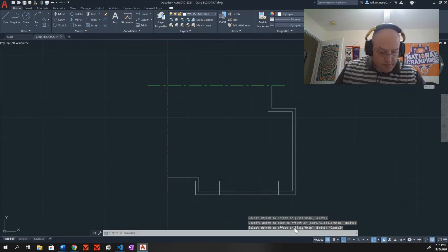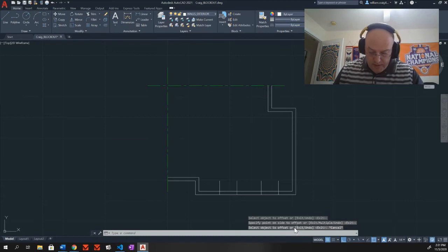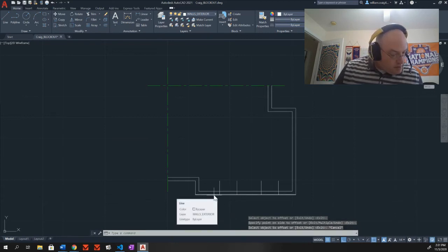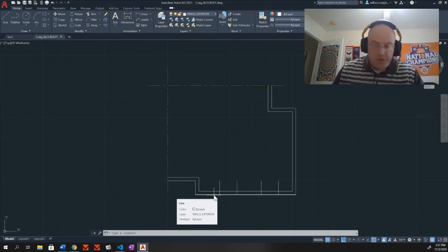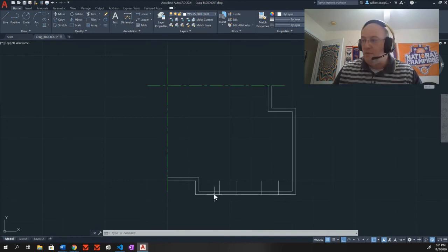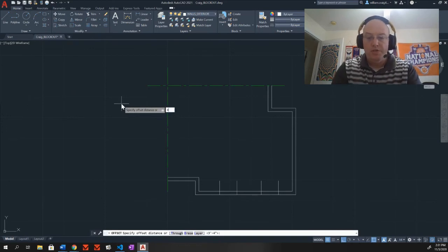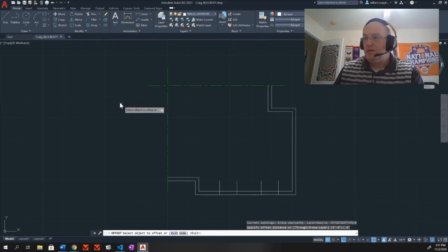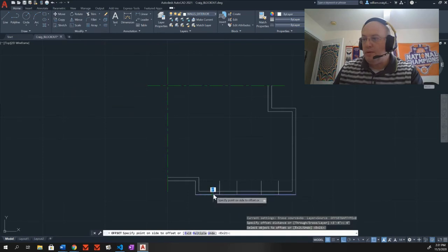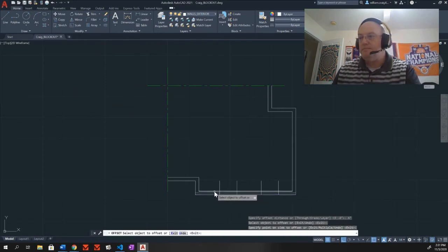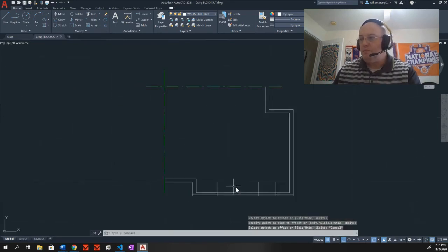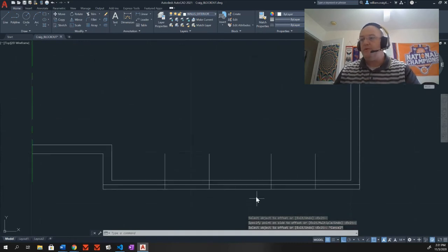And we're also supposed to offset this bottom line right here. As it says, assume that the glass is at the middle of an 8-inch thick wall, so we should be offsetting this by 4 inches. So offset tool, 4 inches. I take this exterior wall and bring it in 4 inches. Press escape. Zoom in a little bit so y'all can see what we have here.